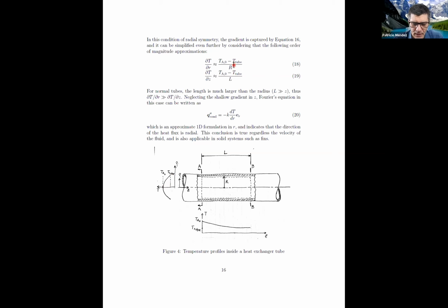That's more or less what the gradient is. And you see, the issue is not so much the math here, it's what this math means. Longitudinal gradient, similar story. I start at the center with a high temperature, and at the end, eventually everything is in equilibrium. So I would have more or less the same delta T, the same difference in temperature between inlet and outlet, but in this case divided by the length of the tube.